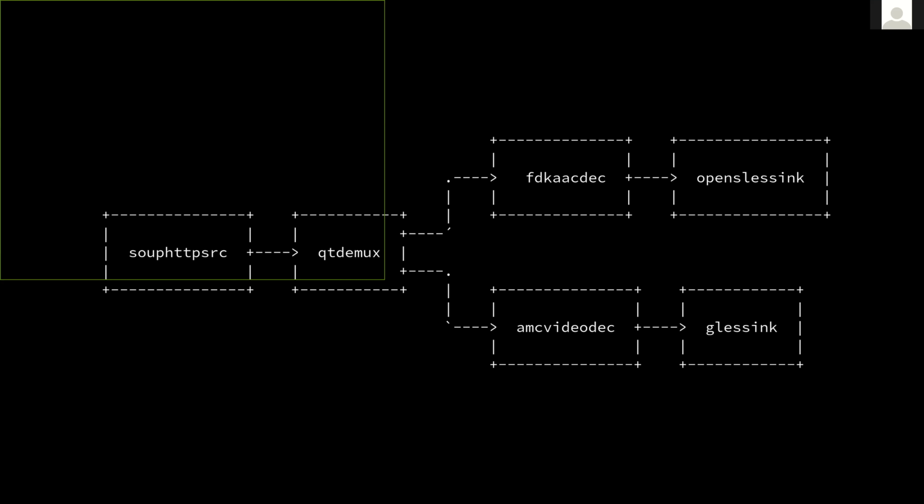And things get a little more interesting when you want to deal with video, right? So if this is running on Android, presumably this is on a mobile device where we want to be power efficient, right? So we want to use the underlying hardware's and platform's ability to provide accelerated video decode services. And that's usually a decoder block alongside the GPU. And we also want to render it without having to take that memory from that decoder block back into the CPU and then give it back to the GPU again.